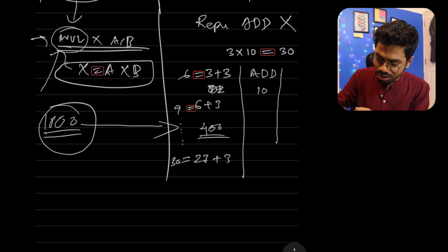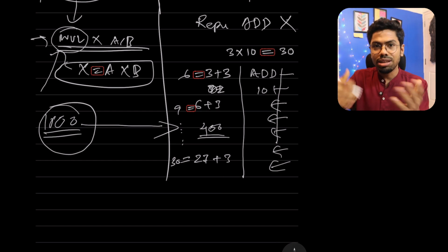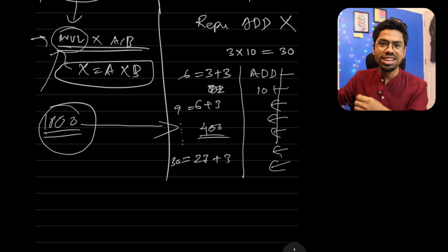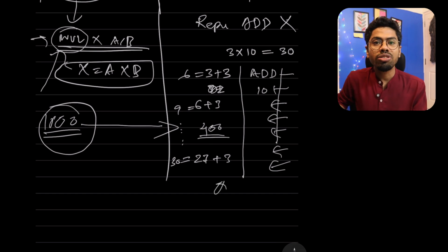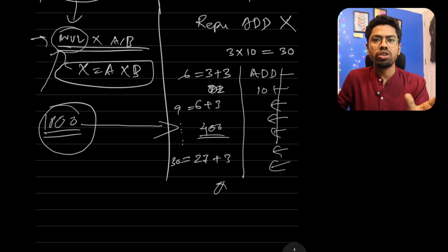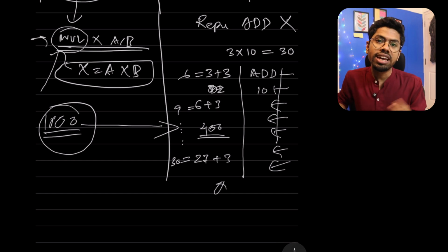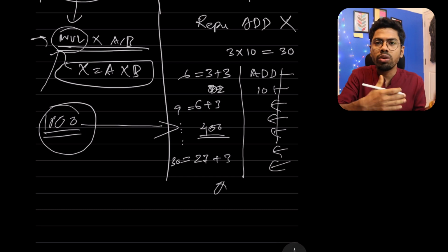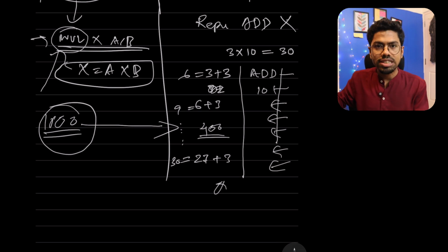But again, for a simple multiplication, ARM needs to do 10 separate decoding, fetching and storing operations. There are a lot of things going on behind the curtain. So ARM might also need the same amount of time to do this. Therefore the microarchitecture defines a lot of things, because without seeing the microarchitecture, we can't say that CISC would be quicker or more efficient than ARM or vice versa, or in the power sense also.